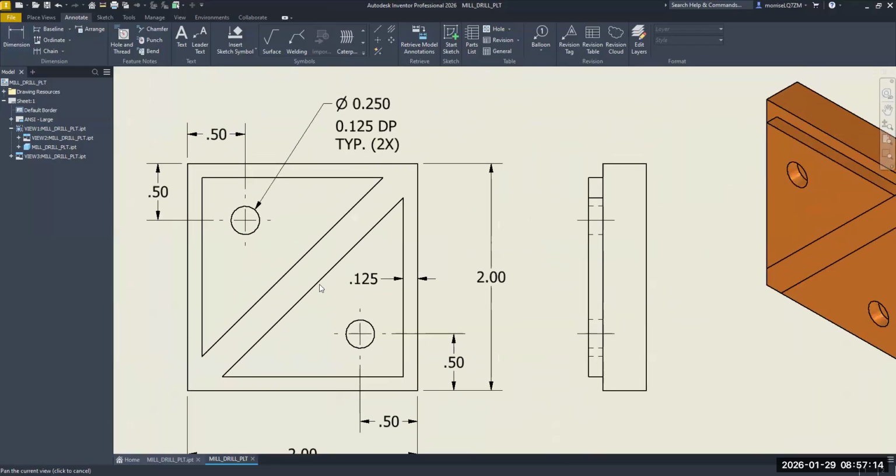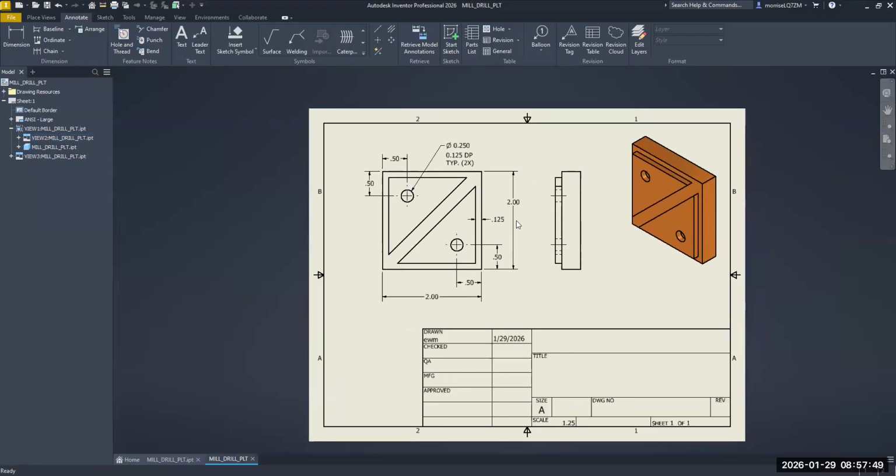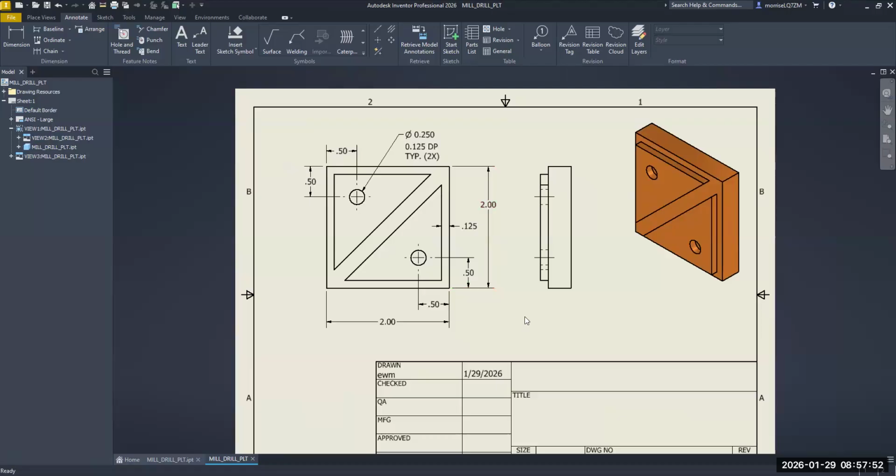Mr. Morris does not like for you to place dimensions on the part if you can keep from it, Zaya. So here's what I'm going to do. Watch. First, I'm going to highlight this dimension, hold down my left mouse button, and move it up a little bit. Why? Because I'm going to move this out here. I did that. Raise your hand if you're able to do that, okay?